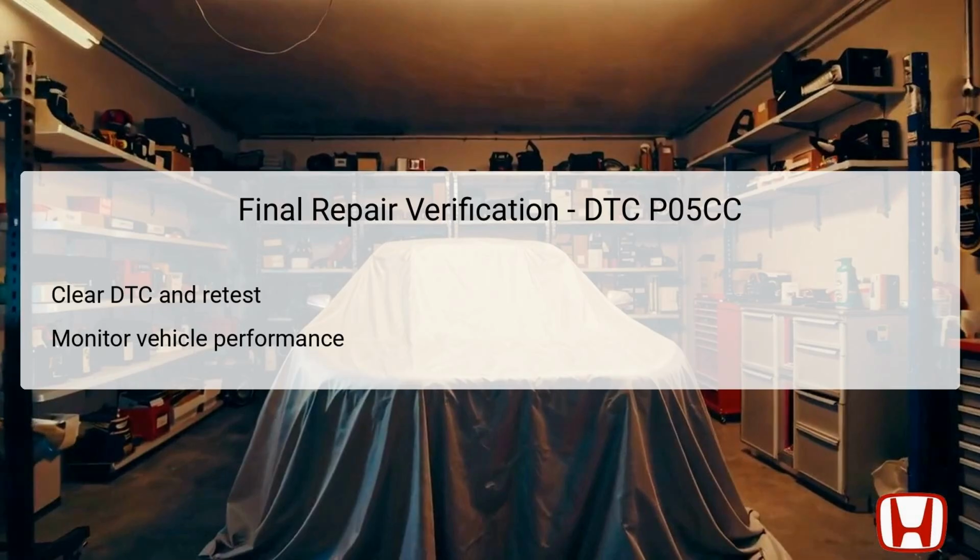It's important to monitor the vehicle's performance during this phase, especially focusing on smooth acceleration, normal idle behavior, and the absence of warning messages on the dashboard. This step confirms that all previous issues have been effectively resolved and that no new codes emerge. If the DTC reappears, it may indicate the need for further inspection or a deeper investigation into unresolved problems.